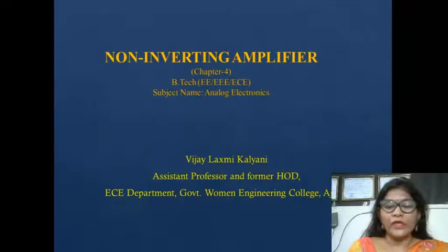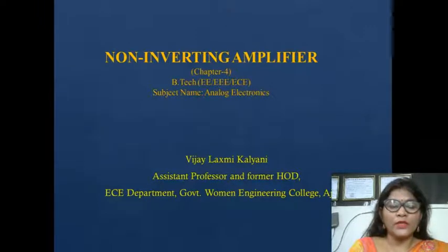As we have already discussed in our previous lecture, the problem with an op-amp is that the output gain of an op-amp is very high in an open loop configuration, and that makes the op-amp unstable and difficult to control. Therefore, to overcome this problem, closed loop op-amp configuration has generally been considered.